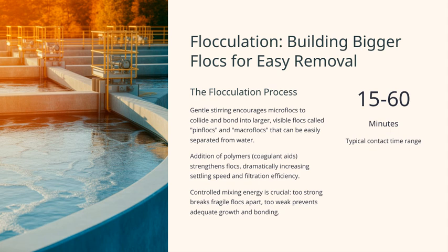Now, let's take a closer look at the flocculation process. Gentle stirring is key here. It encourages microflocs to collide and bond, forming larger visible flocs known as pinflocs and macroflocs that are much easier to remove from water. This process is crucial because larger flocs settle faster and are more effectively filtered out.